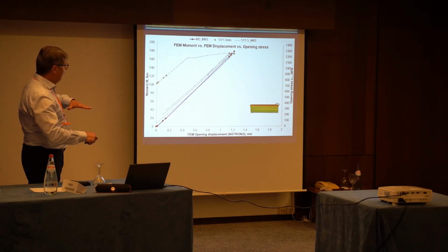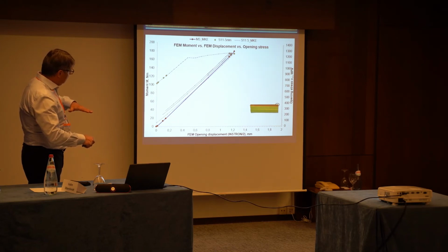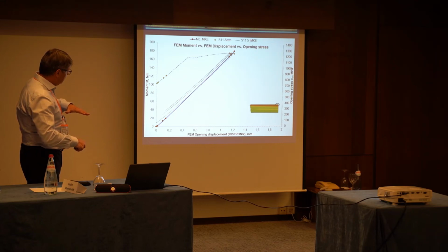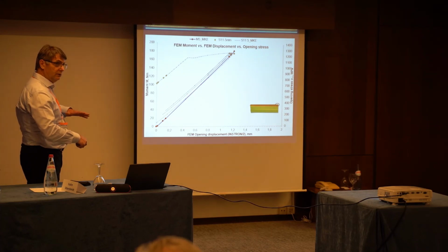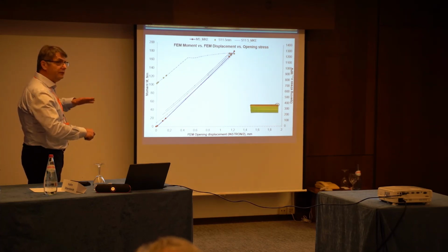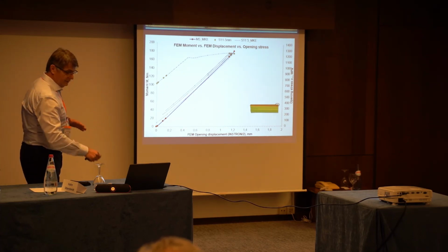So if you now do the unloading from this point, you go down, and the result of the finite element computation is going to give you this, let's say, relaxation. And if you repeat this, you will see that from this line you will get different unloading curves, because you always have some different shift in plasticity.